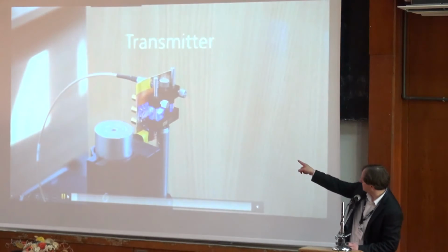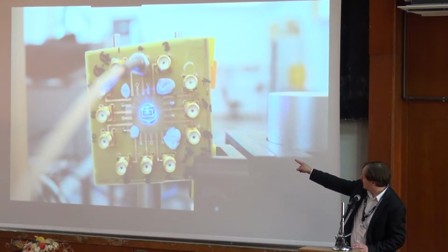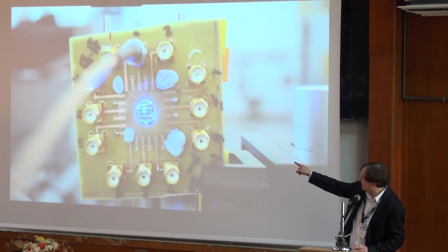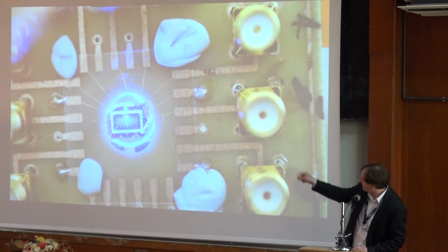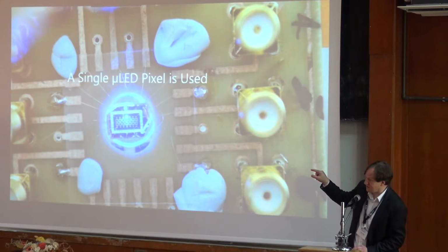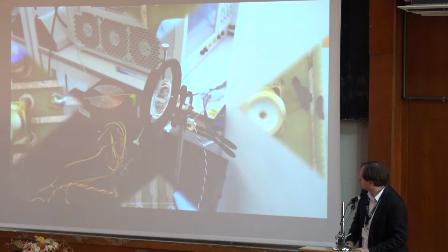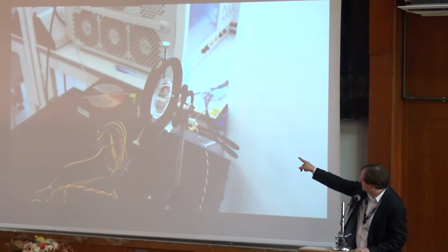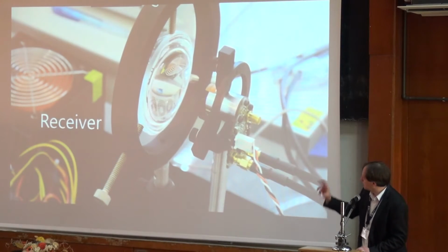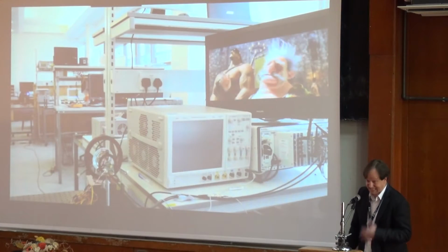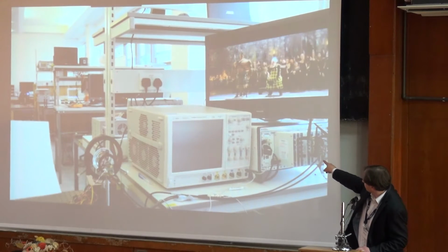So here's the little lens, it's a little beamformer, costs less than $1. And this is the micro LED. It's the micro LED array. In fact, it's 20 micro LEDs, but we use only one here. And that is connected to a National Instruments PXI, which is a full physical layer OFDM implementation. So this is the receiver. It's an APD with a 7 centimeter sized lens, polymeric again, a beamformer. And you see the LED there. This is the transmitter, and this is the high